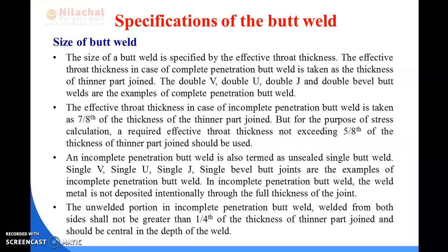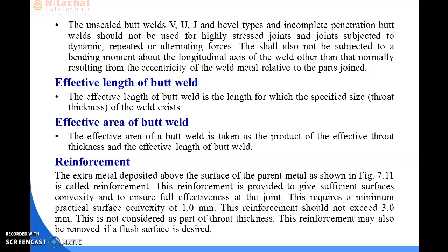Okay. So now comes to some specifications of the butt weld, like the effective length of the butt weld. So here the effective length of butt weld is the length for which the specified size, that means the throat thickness of the weld, is achieved.